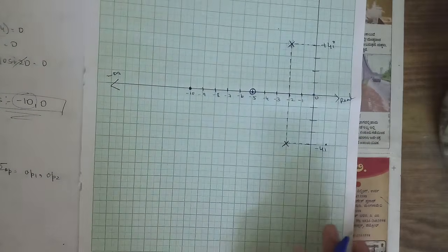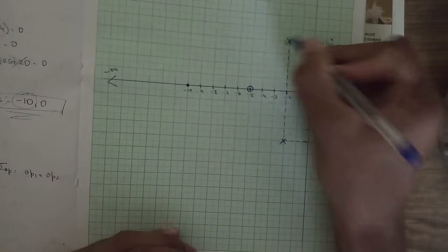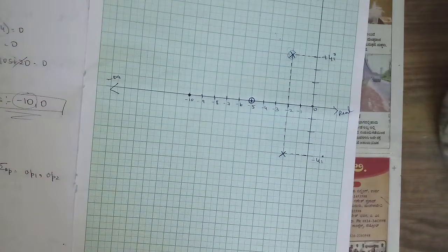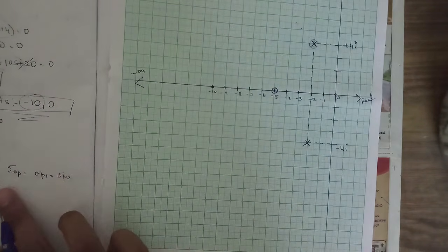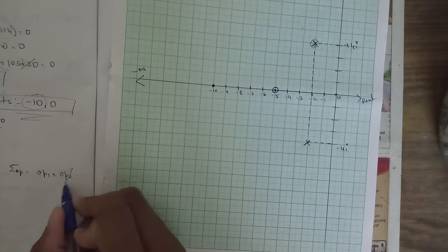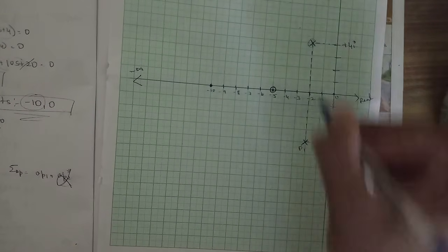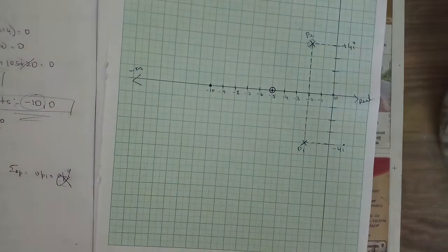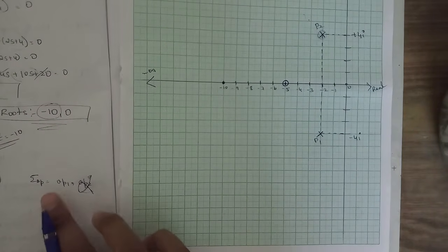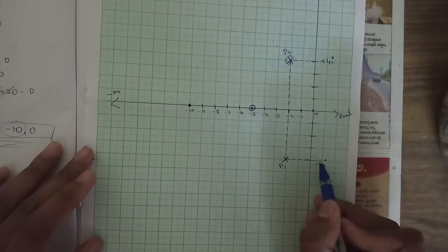Here we are finding the angle of departure with respect to this pole now. So when we are finding summation theta p, it's not required that we need to find this angle theta p2. Let's name these poles p1 and p2 in general. So just try to find the angle of theta p1 with respect to the pole 2 and the origin.